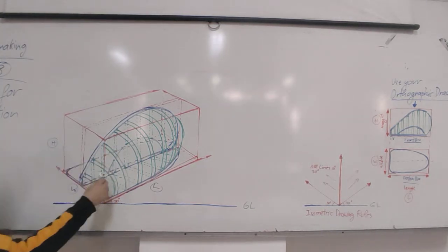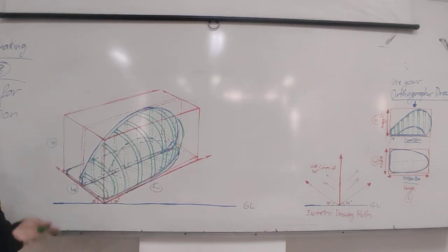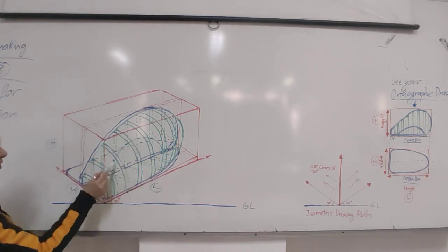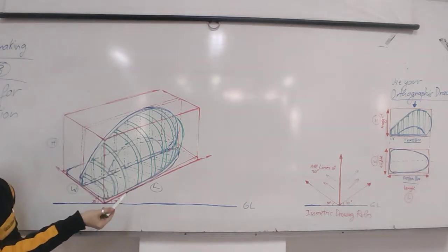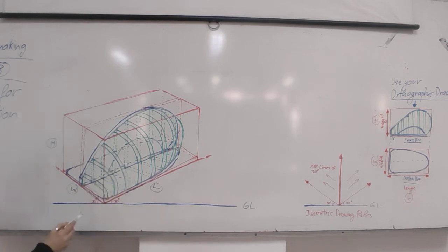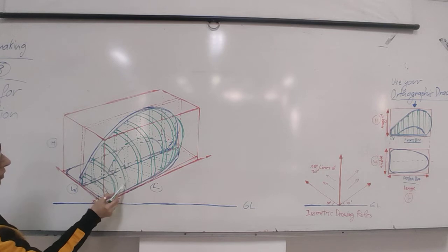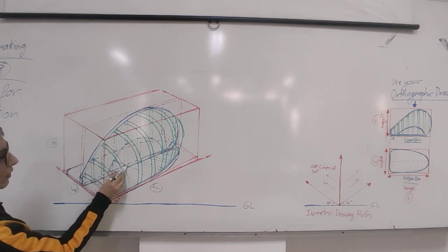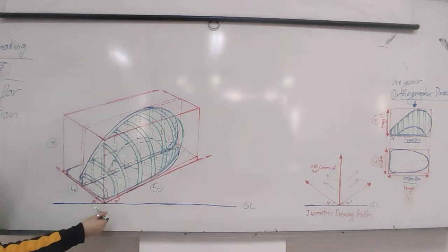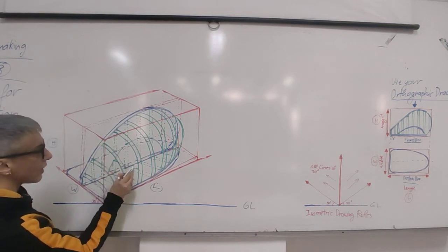Now, this line here in the middle view, where there is a sudden change of the shape, we need to identify it. It's located here on this view, but where is it located on these? So we need to take dotted lines out, the same thing we did here, like here is one of them. Dotted lines, be careful to be exactly parallel to the rest at 30 degrees, okay? So it starts here and ends here.